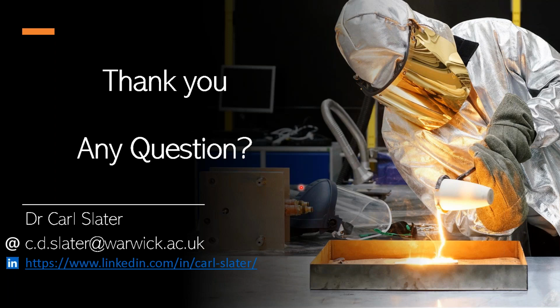Okay, yeah, so it's fairly simple, particularly because we know the direction of the deformation. We're looking at the x direction over the y direction on an SEM. We're just measuring those two lengths, and then for a known deformation of 30%, we know what a sphere should deform into, so we have an idea about what it should be if it was perfectly deformed. Then the aspect ratio is that ratio between the length over the height.